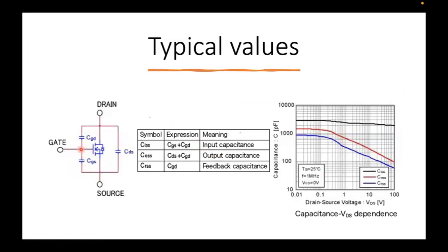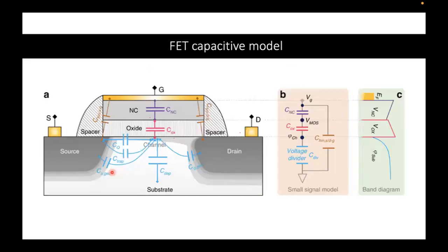You can make another one between the gate and the drain, and finally another one between the drain and the source. So this is how we can rearrange the capacitance to be in terms of nodes on a transistor level, rather than in terms of the MOSFET schematic in a solid state subtransistor level.